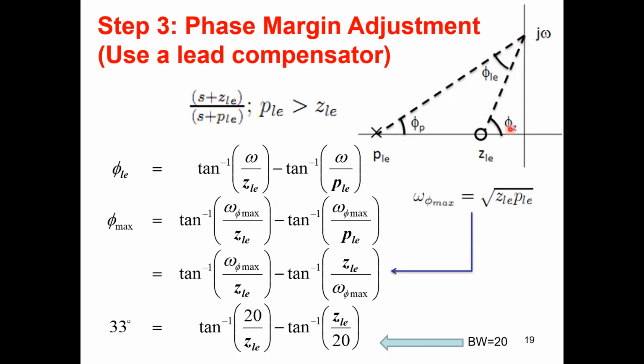Now we are trying to understand what this guy is, the lead compensator. Now if you look at very high frequencies, when j omega is up in the sky, you move it further up and up and up, then what will happen to these two angles? Closer to 90, and again the difference becomes 0.